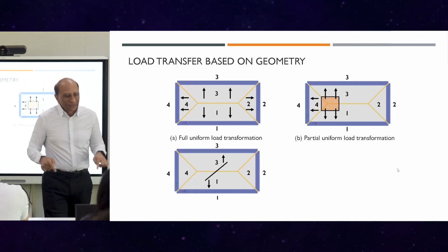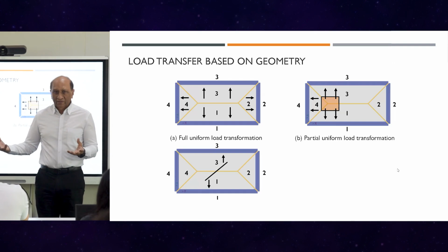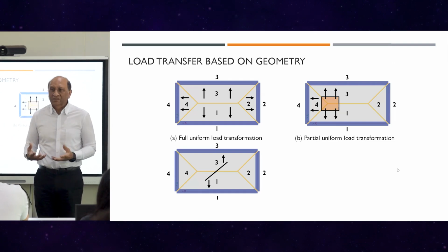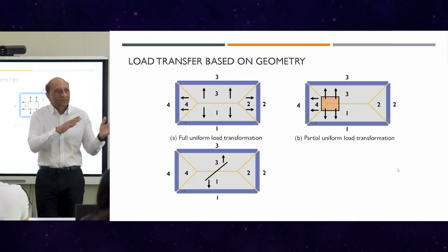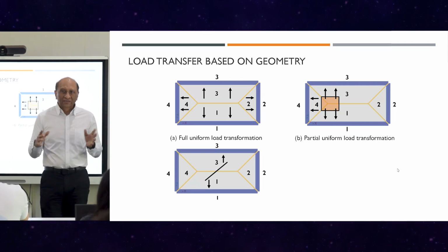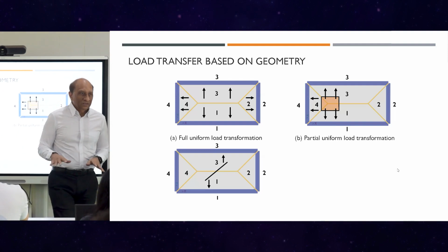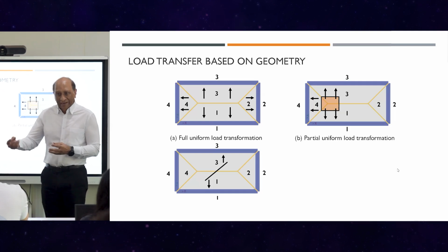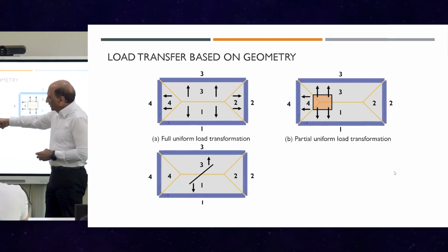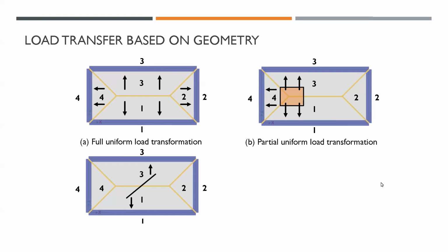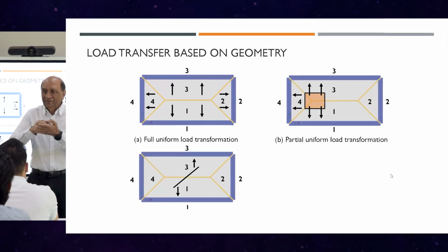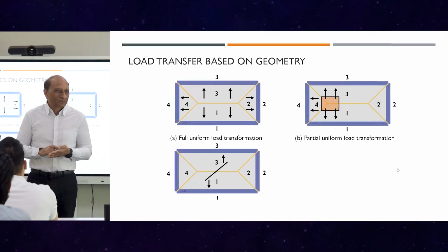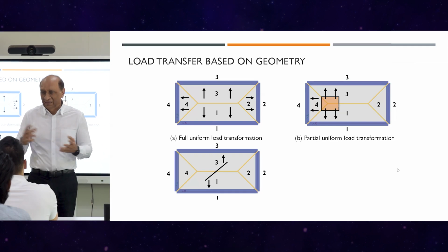So the floor was assumed to be like a table, just resting on the columns, but it didn't participate in the stiffness distribution or calculation. Only lateral loads were considered and the frame was considered. Slab was not part of the analysis. So there was no way for ETABS to determine how to calculate the beam load and the column load. So they had this manual where they showed many diagrams of the internal mechanism they were using to compute. The programmers wrote hundreds of cases, for each case, handwritten formulas on how to transfer the load. It was so much work and still could miss some cases.